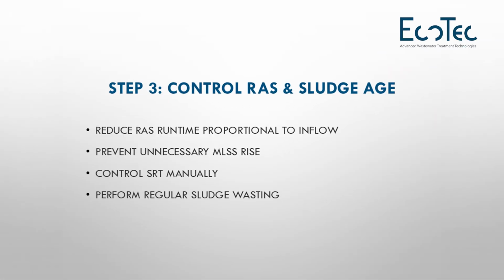In activated sludge processes and extended aeration systems, there is something called a RAS pump. This pump continuously pumps sludge from the clarifier into either the collection tank or the anoxic chamber. This also has to be tweaked during low load operations.